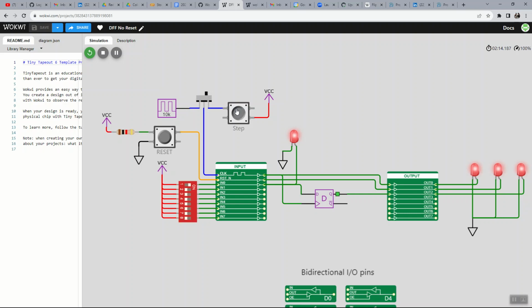As soon as I press that button, it assigns Q from D, and now it's high. Now I can turn off D as much as I want, turn it back on, and nothing happens to Q until the next clock cycle.